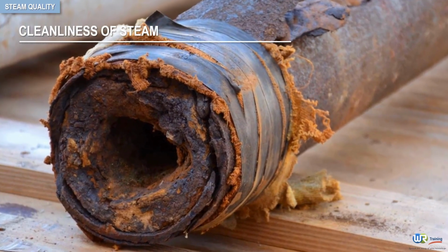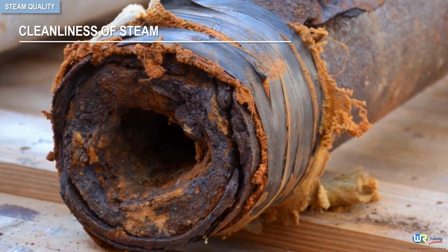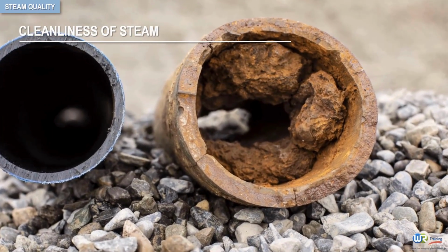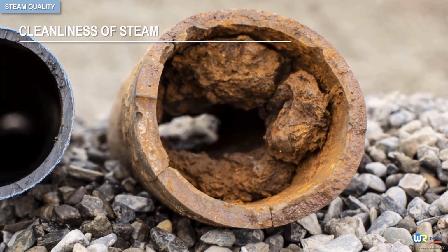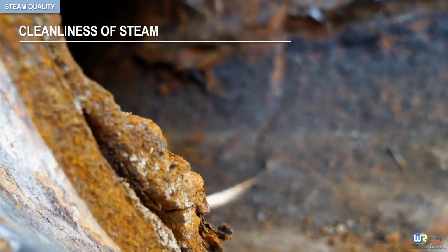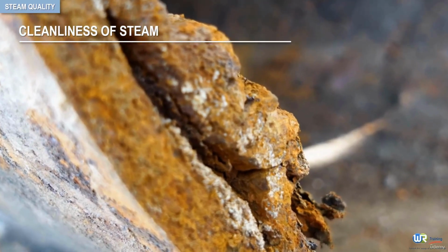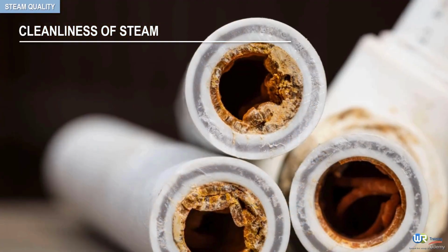Layers of scale found on pipe walls may be either due to the formation of rust in older steam systems or to carbonate deposit in hard water areas. Other types of dirt which may be found in a steam supply line include welding slag and badly applied or excess jointing material, which may have been left in the system when the piping system was initially installed.